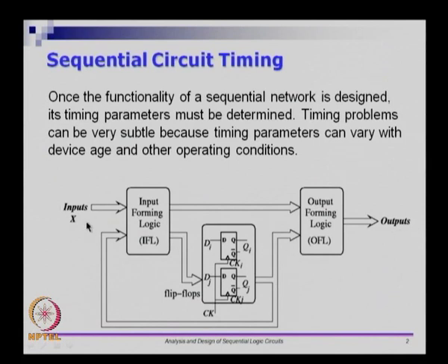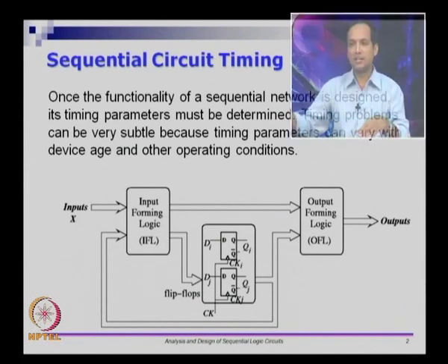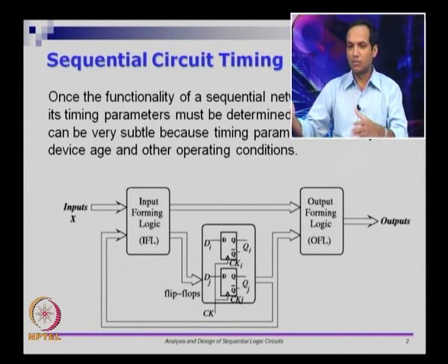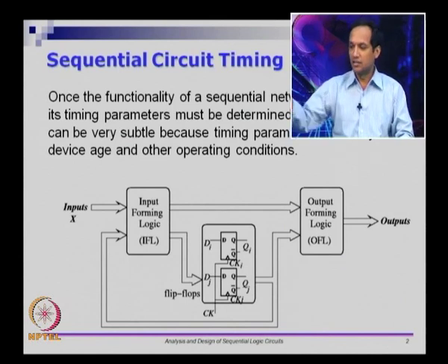A signal that is placed on the chip's input will take some finite amount of time to go inside. It has to go to the input logic which is inside your chip, and it has to go to the state register which is again inside your chip. Finally the output that is coming out from your chip has to travel through the bus that is in the printed circuit board or the motherboard, and then go to another device. So there are quite a few things that happen in the system.